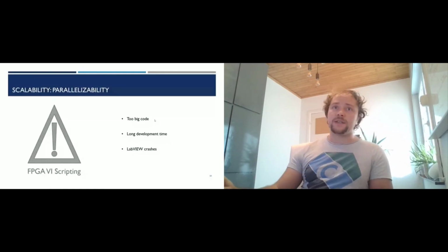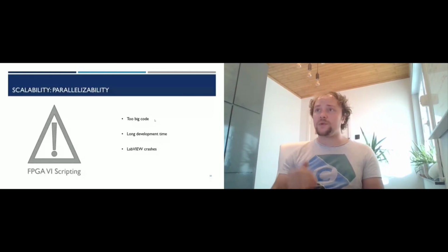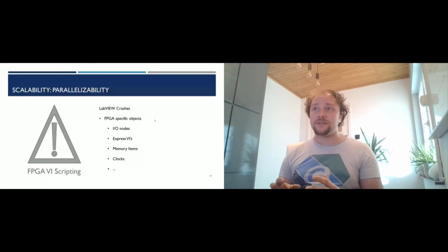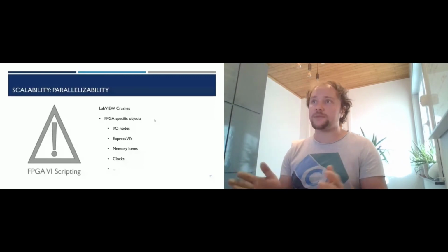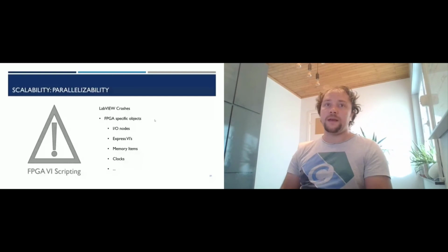The LabVIEW crashes I found happened whenever I tried to access FPGA-specific objects: I/O nodes, clocks, memory items. So it took me a while to figure out a strategy to make sure the crashes didn't happen, and it just meant staying away from those, just using normal VI objects or G objects, multiplication, for loops, while loops, feedback nodes, whatever.